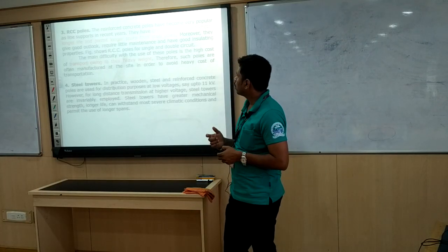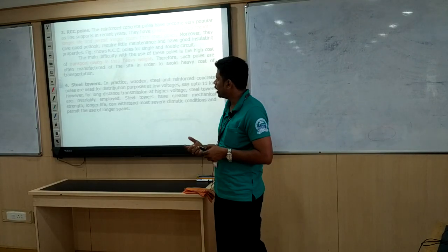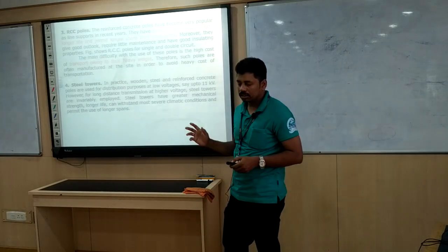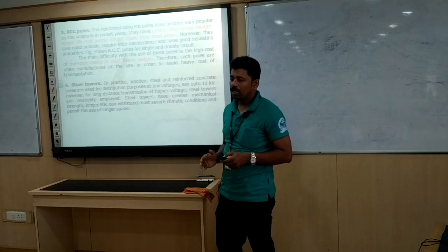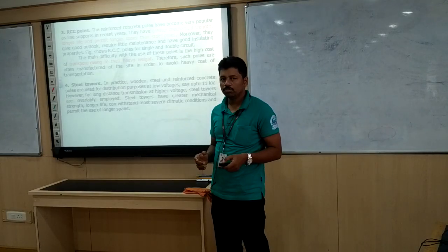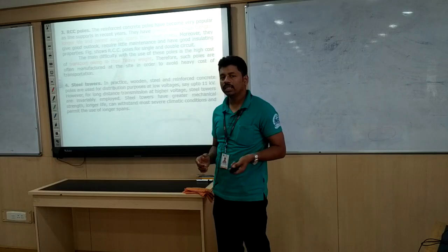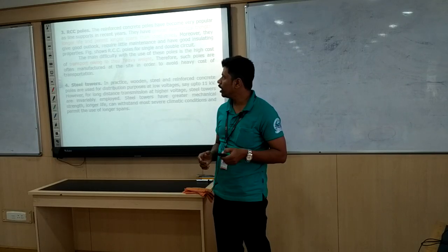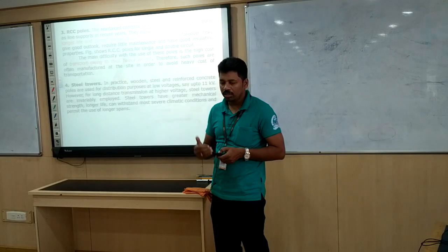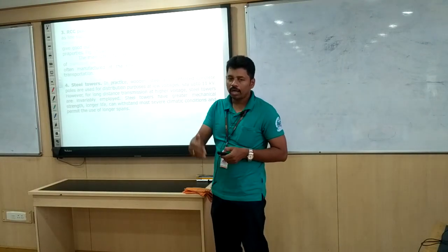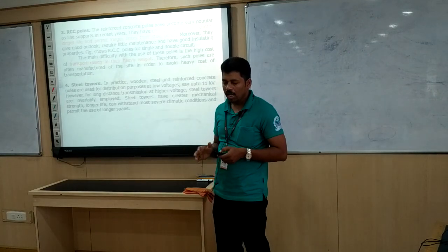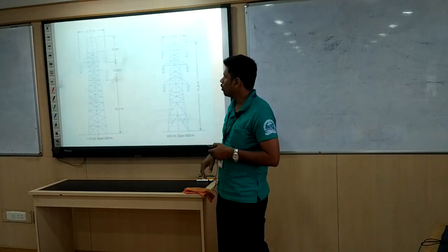Reinforced concrete poles have become very popular for line conductors. Wherever you go across the road, you can definitely come across these RCC poles. That's why I'm saying, starting from 230 volt single phase distribution, 415 volt 3-phase distribution, 11 kV primary, and 33 kV primary distribution, up to that we are using RCC poles. Beyond 33 kV, starting from 66 kV, 110, then 400 kV, 765, 1200, everywhere we have to go for steel towers. Accordingly, the height of the tower will be more.